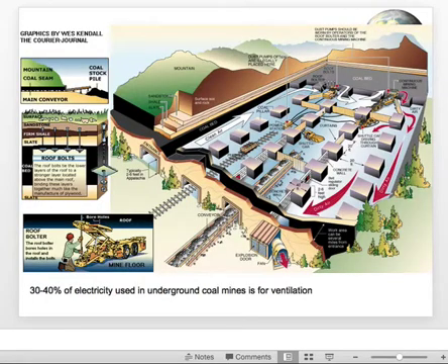So here's a more reasonable, again shown on a very small scale. The real scale is considerably larger, but here you can see the fan. The fan is always offset in case there is an explosion, because it's an important component for the recovery process and could save lives, and so you want to ensure it's not damaged. This one is pulling air. Sometimes there's a secondary one pushing air in.